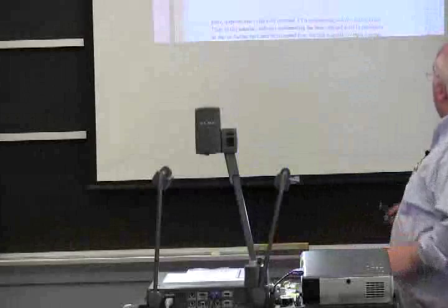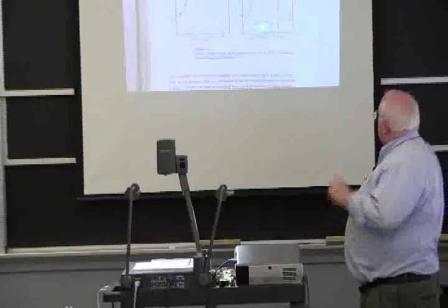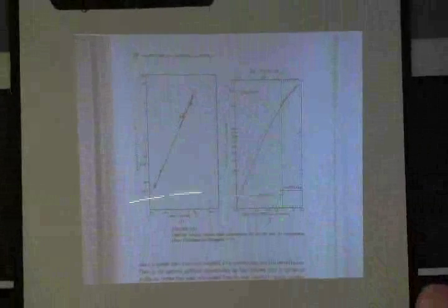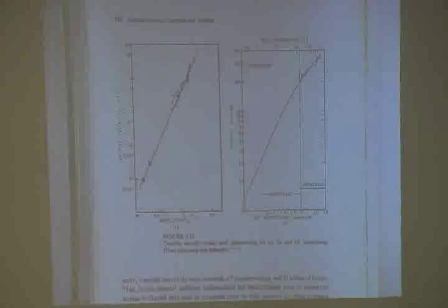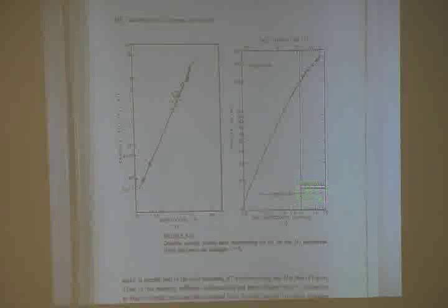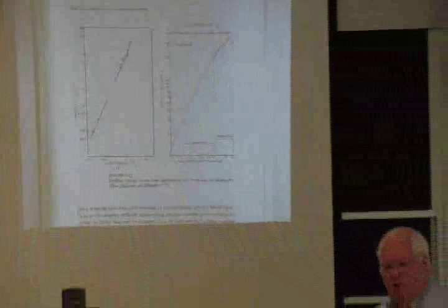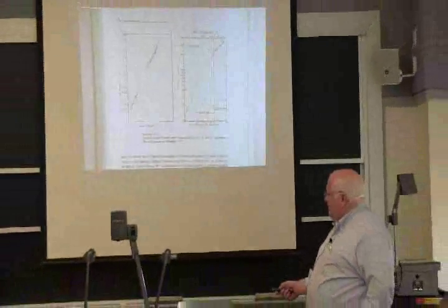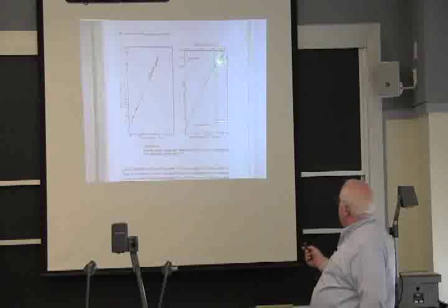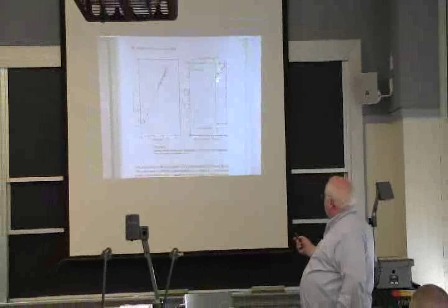So this actually is a plot of melt supercooling, where you undercool, and it's normalized to essentially this delta T equals to the heat of fusion. When you're below 1 on the normalized curve, you're hypercooled, which means you've extracted more heat from the liquid than the heat of fusion. And the reason we can do this with phosphorus, phosphorus doesn't have a very big heat of fusion, doesn't take a very big delta T. In fact, the delta T here is on the order of 20 degrees or so.